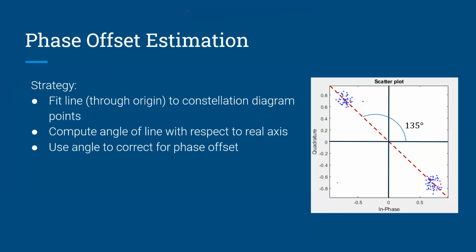So here's where a packet header comes in. If you're rotated the wrong way, then your bits will be flipped essentially. And if you make your header in such a way that it's not identical if you flip the bits, then you'll know which way is the right way.